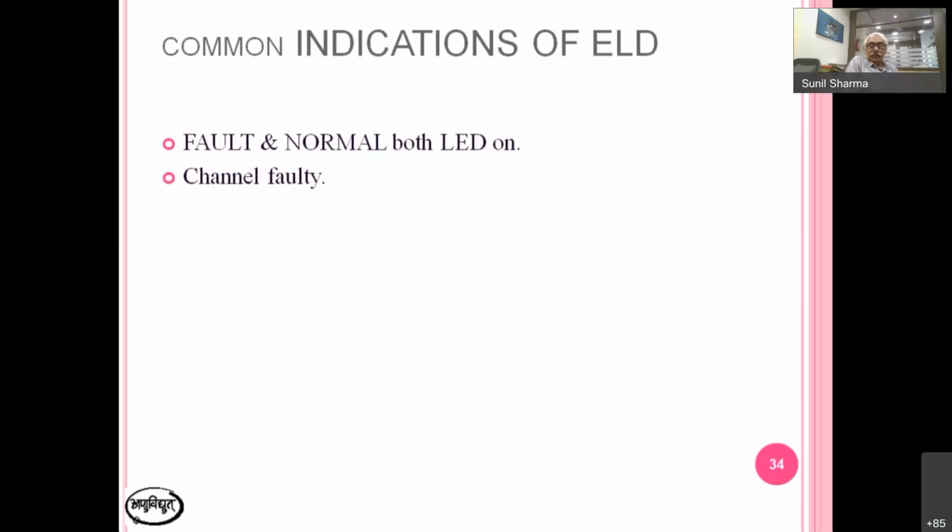Now the reverse case: the fault and normal lights are both on. In that case, the channel is faulty. Just switch it off and disconnect it. Don't use this channel, because the channel has become faulty.